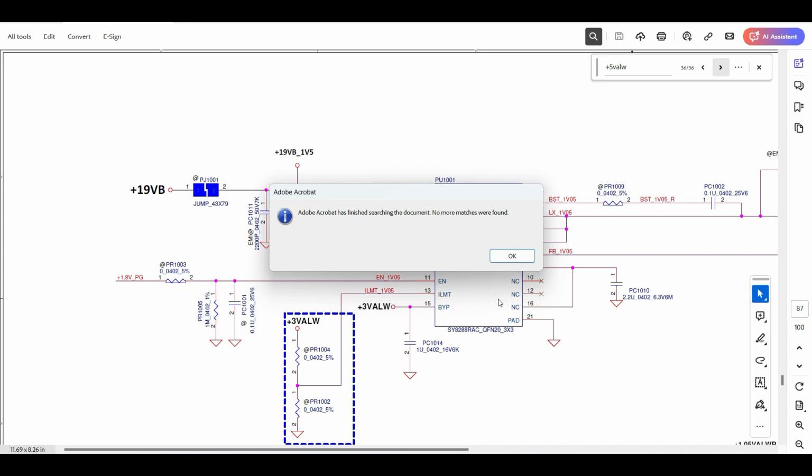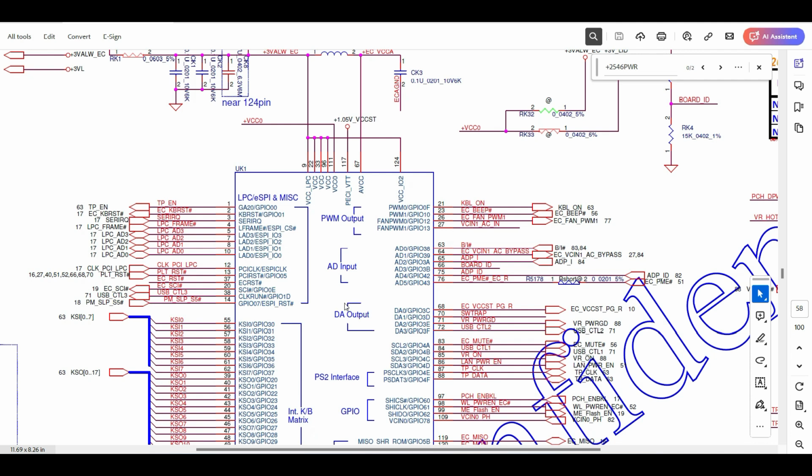So now what are the basic voltages, everything I explained. Now what will happen? All basic voltages, S5 stage voltages, all signals and voltages are present now. In this condition, once the IO releases the power enabled signal, PCH power enabled signals, almost all PCH section blocks get enabled. Now even the PCH is enabled, and here I also enabled. Here one more signal will go to PCH. What are those? Not only one, a little bit multiple.